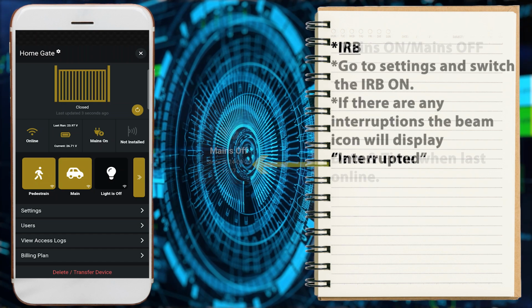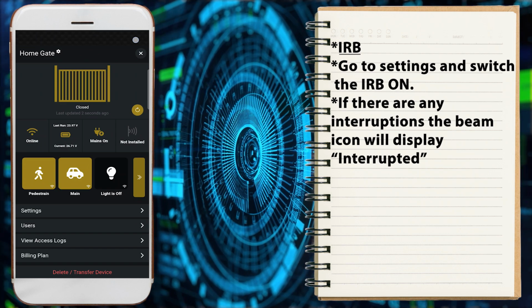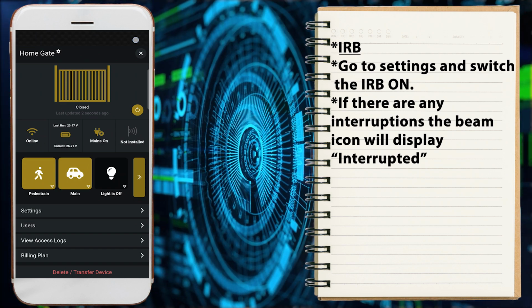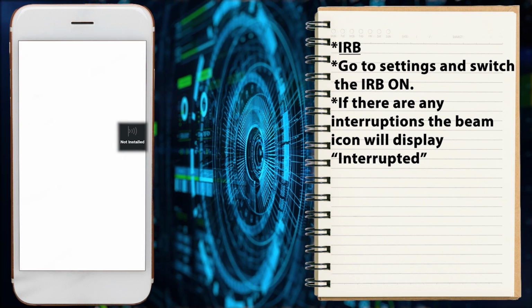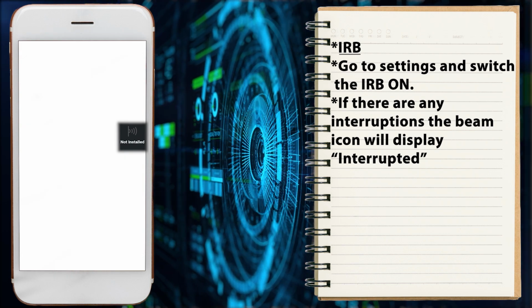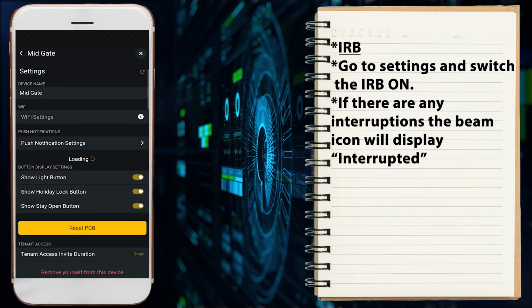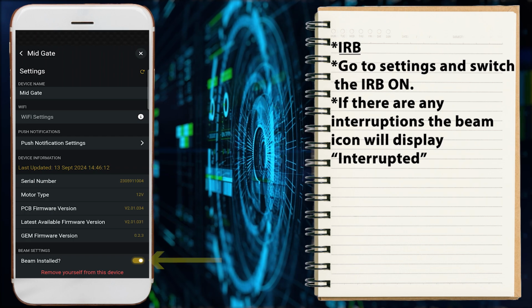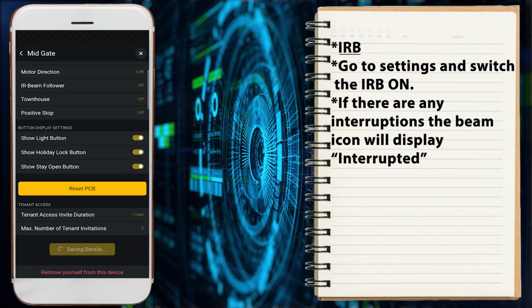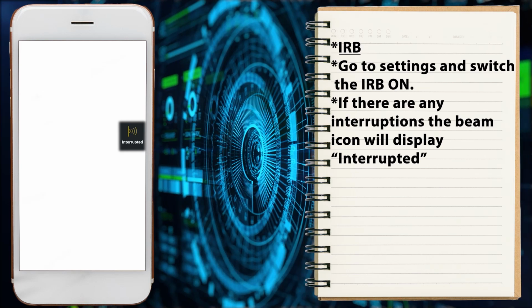The IR beam icon must be activated in the settings menu if IR beams are installed on your gate. If the IR beam function is not enabled, the status will display as not installed, as demonstrated here. To enable the IR beams, navigate to the settings menu where you will find the beams installed option. Simply toggle this setting to on and save your changes. Once the beams are installed and the IR beam function is activated, the system will detect any interruptions and display it here.